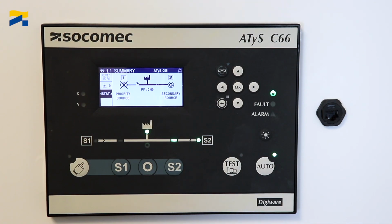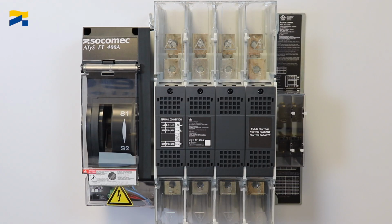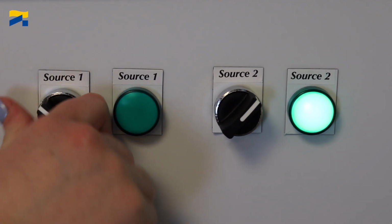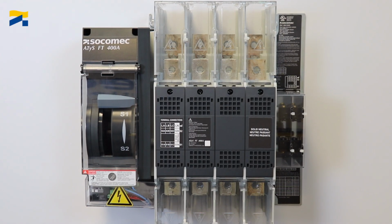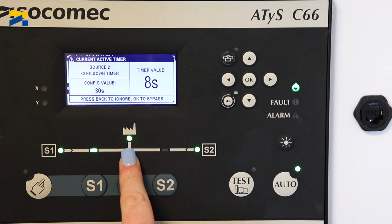Once the timer is complete, you heard the noise of the ATyS FT switching to source 2. You can now see that the manual handle is on source 2 and the LEDs indicate that the load is supplied by source 2. When I switch source 1 back on, the ATyS FT will switch back to source 1 to supply the load. This happens because in step 6, we set the source priority to source 1, meaning source 1 is the preferred source and the transfer switch will automatically transfer to this source as long as it is available. The manual handle is back at source 1 and the LEDs are lit up for source 1 and source 2 and the load is supplied by source 1.